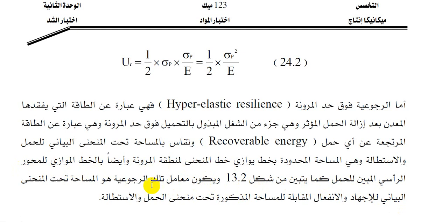The resilience coefficient, or modulus of resilience, will be the area of the stress strain curve corresponding to the area of the load extension curve.